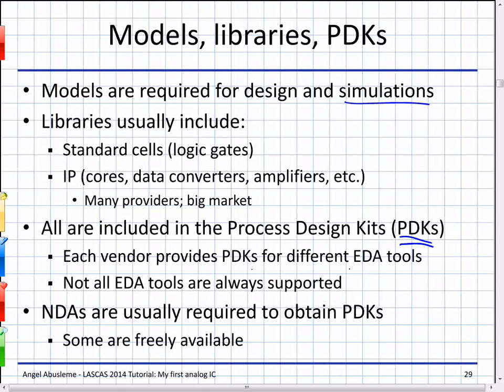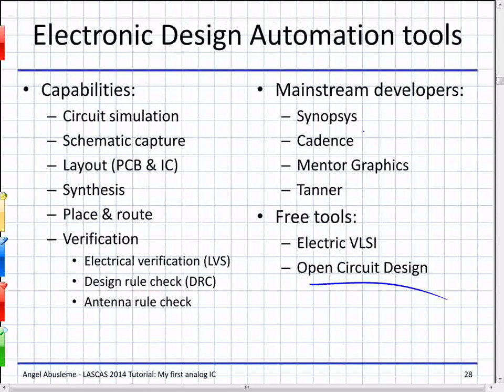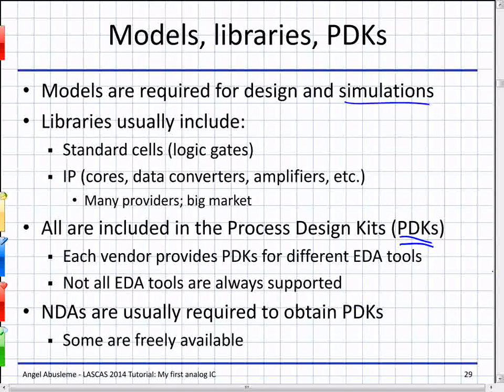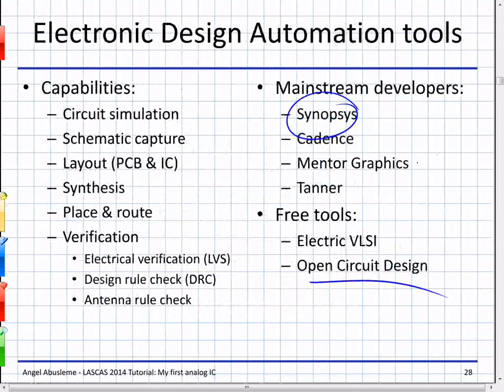Each vendor provides PDKs for different EDA tools. For example, if you decide to work with Synopsys, you need PDKs for Synopsys. If you decide to go with open circuit design, maybe you can find some free PDKs. Not all EDA tools are always supported. For instance, only a few processes support Mentor Graphics. So if you want to go with Mentor, you can't choose any process.